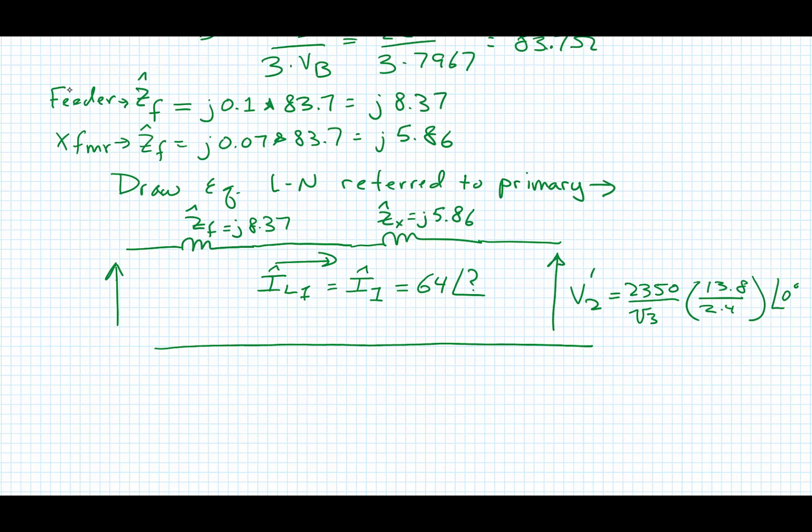So what I see now is we are going to have the power factor angle to solve this problem. This is the feeder voltage line to neutral right here. What is this angle? Well, there are no branched impedances, and so that angle is the power factor angle. So we know that it's a lagging power factor.